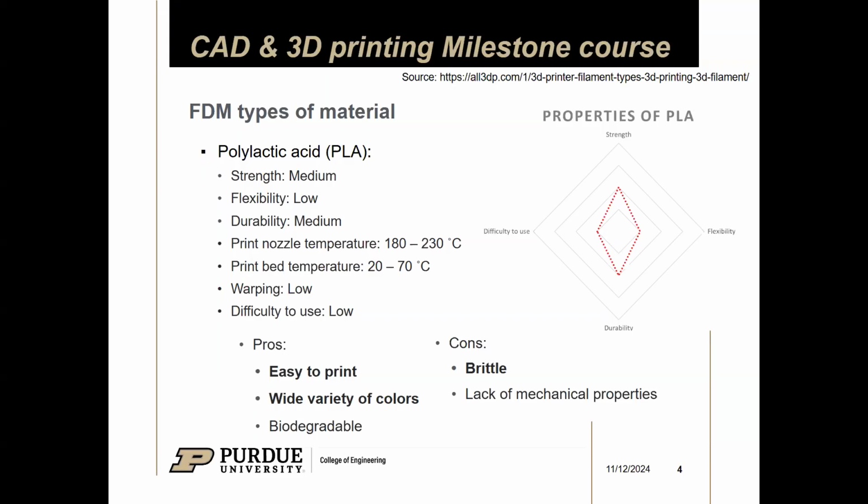As a material, it's actually really, really rigid, which is pretty nice. So if you want something to be nice and rigid, then PLA is a pretty good material. I would say the main drawback for PLA is its temperature resistance. So I print with this printer right here, and a lot of the components on the gantry are 3D printed. But because it's fully enclosed, the chamber temperature will get up to 60 or above Celsius. And if I printed the gantry in PLA, it would start to warp and then I'll be all sad, right? So I don't want that for my printer.